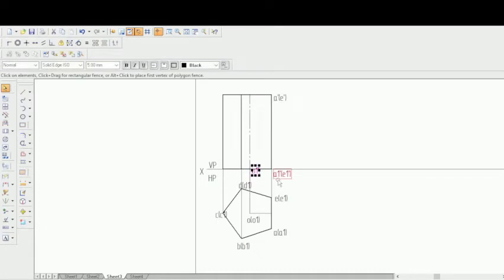See that it's mentioned using brackets. Let's mention that using brackets because it's the axis, the middle point. The middle point usually will not be visible whether you see from the front view or wherever. So when you see from the front view, it will be hidden. So O dash is also mentioned within the brackets, and this will be O1 dash.